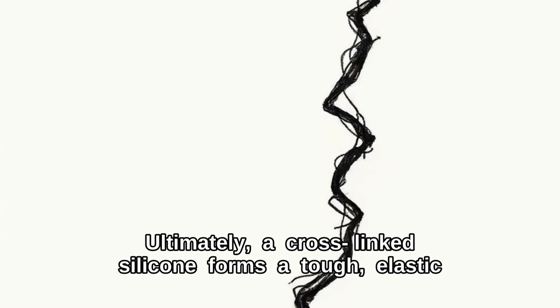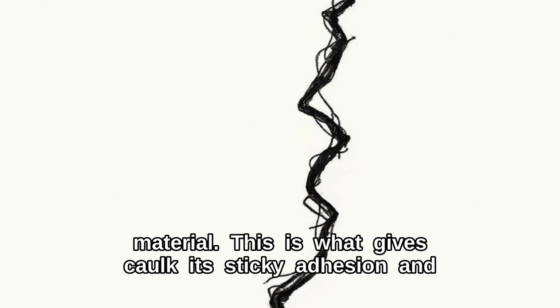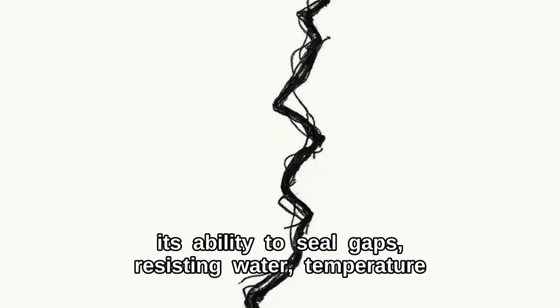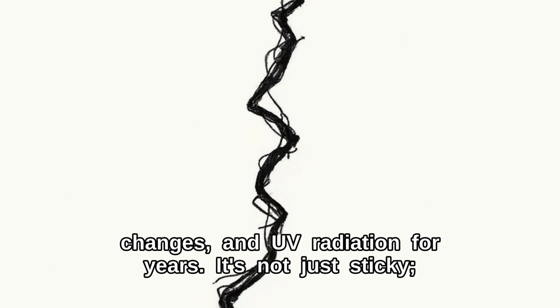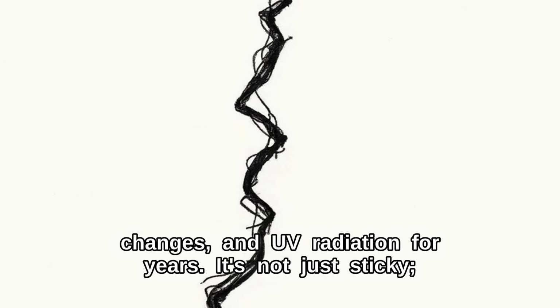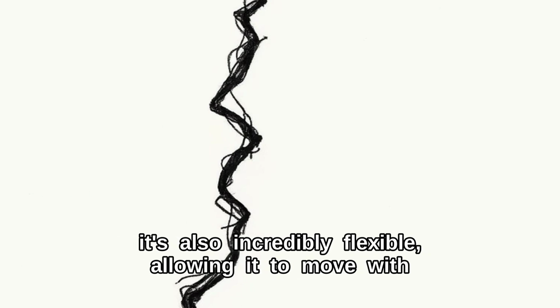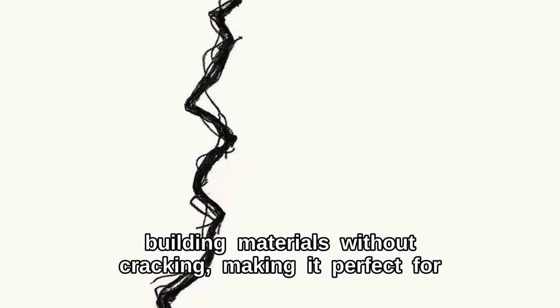Ultimately, a cross-linked silicone forms a tough, elastic material. This is what gives caulk its sticky adhesion and its ability to seal gaps, resisting water, temperature changes, and UV radiation for years. It is not just sticky, it is also incredibly flexible, allowing it to move with building materials without cracking, making it perfect for sealing windows, doors, and bathroom fixtures.